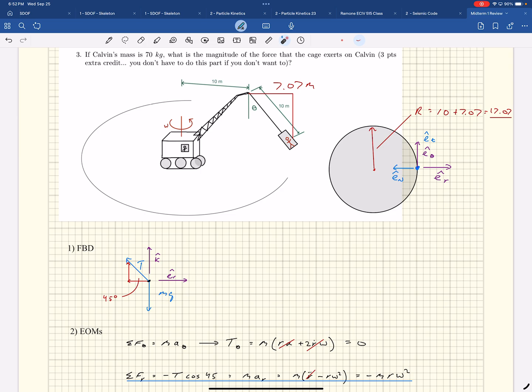Yeah. It gets really complicated. And that's why the example in the homework that you did was when the other one disappeared, right? If you sped it up too much, then one of them went slack. And if you slowed down too much, the other one was slack. Because if it's somewhere in the middle, I believe it's indeterminate, and there are other ways you have to solve it. You can't do something like T1 being some percentage of T2. I think it gets too complicated because it depends on the stiffness of the cables in between them, and it gets weird. That's why the homework problem just has one go away and then the other go away. Otherwise, it's indeterminate, because you have too many unknowns to try to solve.